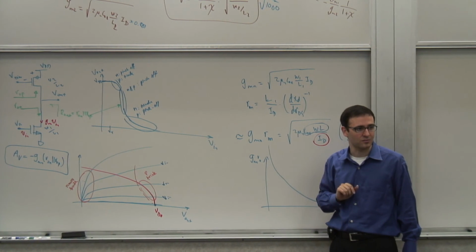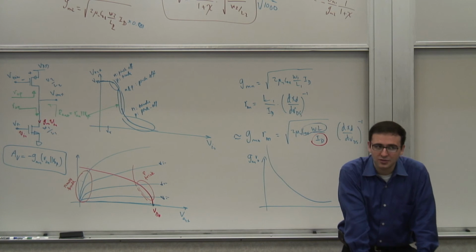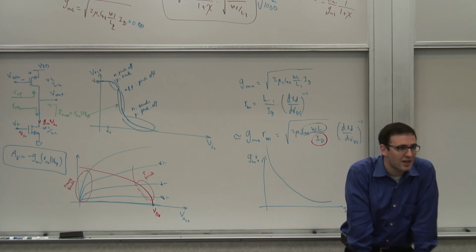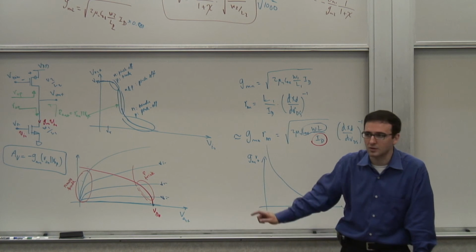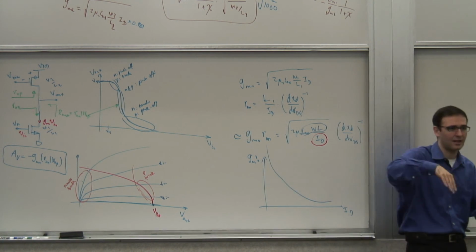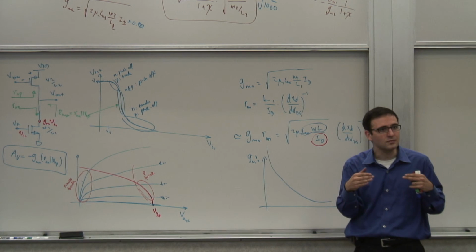in this calculation. Now, we saw that in the subthreshold region, the MOS transistor's drain current dependence on VGS was what? What kind of dependence did it have? It's more of an exponential dependence, right? As opposed to the quadratic dependence. It's in your handouts, and we did the band diagram there. It goes back to the Boltzmann distribution, right? It becomes exponential in subthreshold.